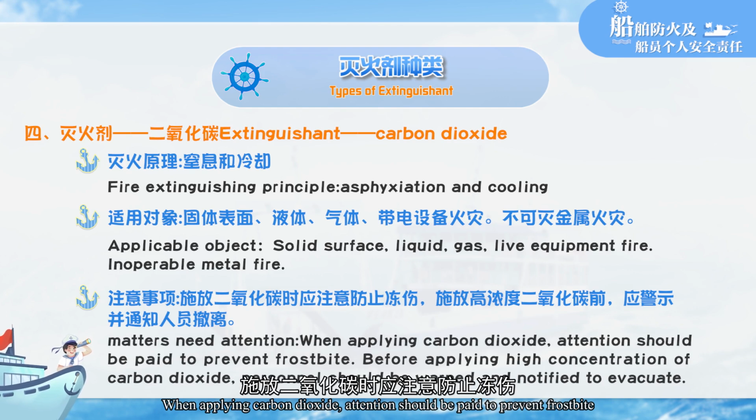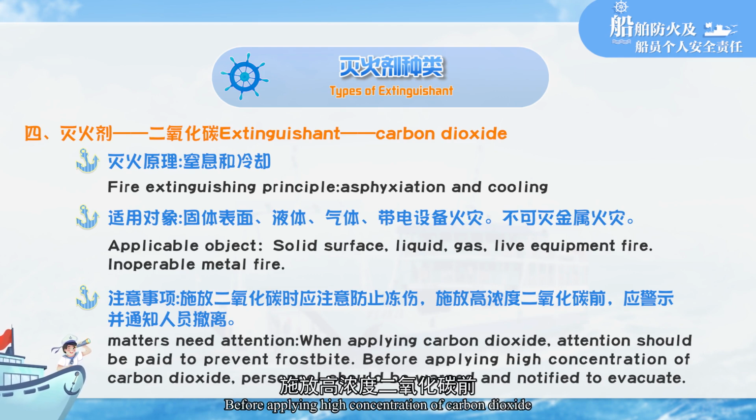Matters needing attention when applying carbon dioxide: attention should be paid to preventing frostbite before applying a high concentration of carbon dioxide. Personnel should be warned and notified to evacuate.